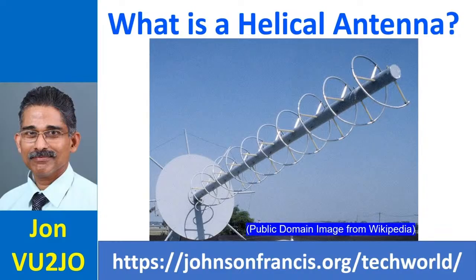If the helical antenna is made of a single wire, it is called monofilar, and bifilar if it has two wires, and quadrifilar if it has four wires. Helical antennas can operate in normal mode as broadside helical antenna or in axial mode as end-fire helical antenna.